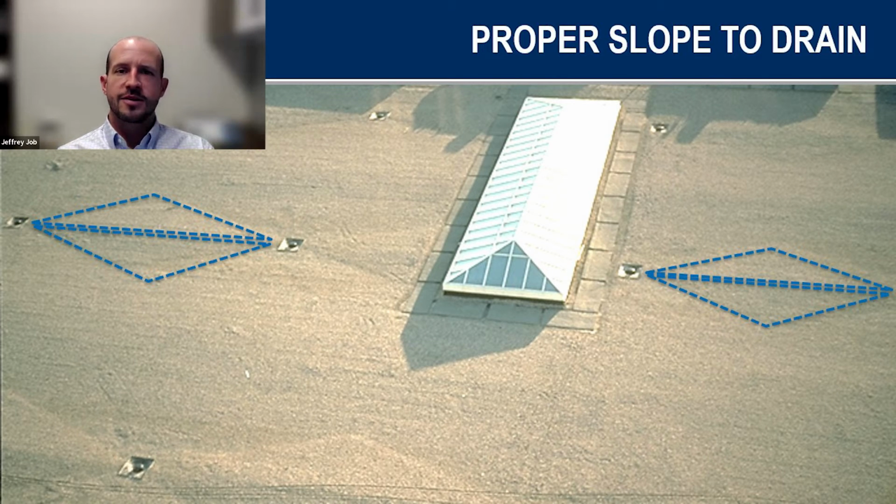And I would say too, from a best practices standpoint, you might have heard the term "fasten one, adhere one," or variations thereof, where in a lot of cases there are multiple layers to a roof insulation package, which is not uncommon. Say the energy code says you need 4 inches of insulation to meet the R value requirements for the location of your project. Instead of doing one 4-inch layer, typically we're going to do two 2-inch layers, and you're going to offset the joints of those boards to help maximize the thermal performance of that system.